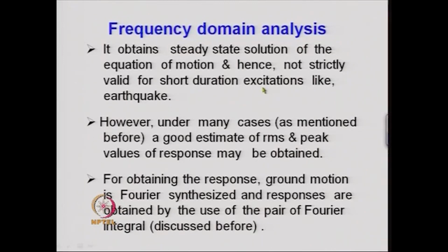Frequency domain analysis in fact provides a steady state solution for the structure. It cannot take care of the transient phenomena, that is the transient part of the response that comes because of the initial state of the system. And therefore, for short duration excitations like earthquake or any other impulse kind of loading, which is a short duration loading, the frequency domain solution may not be applicable, that is the steady state solution there does not represent the true response of the structure.